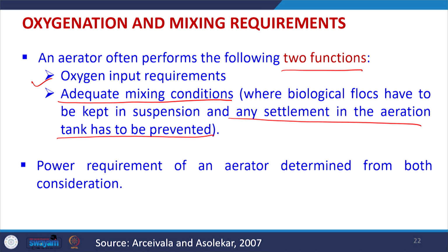So, the aerator performs both functions, and so selection of the aerator is very important. For selection, the power requirement of the aerator has to be determined from both considerations, and then only can we choose the better aerator.